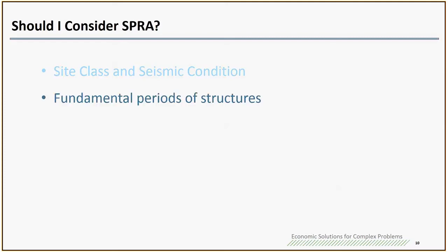Even if you have the structure in site class D and E, you can still take the exceptions to decide whether you need to do the site-specific response analysis. For that reason, you have to have a good understanding of the fundamental period of the structure, but sometimes it's hard to determine that at the beginning of a project, particularly when you don't know what kind of foundation you will use.